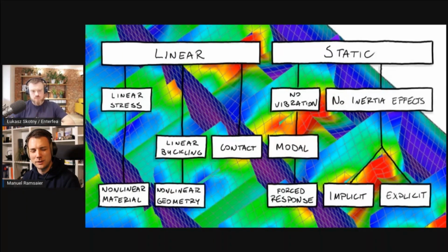And I just recently started digging a little bit deeper into fatigue, because that was not so much on my priority list until now. And I uncovered something with the fatigue scaling, for example. So you have a linear analysis and you get the stresses, and then you have a load cycle, and then you do rainflow analysis over it, and then you can estimate the damage and so on.